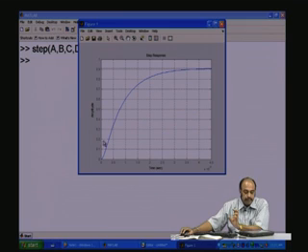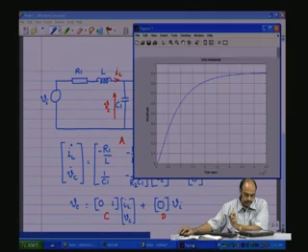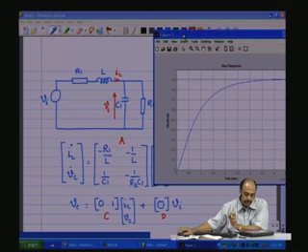So, the voltage across the capacitance would behave in this manner if you apply a unit step of 0 to 1 like this at the input. So, you see that there is an error as I start going to the steady state, the remaining voltage is dropped across R1. If you look at the circuit simultaneously, you will see that here the voltage is 0. Initially, capacitors are short, inductors are open, all the voltages will be dropped across this, and 0 voltage here starts with a 0.